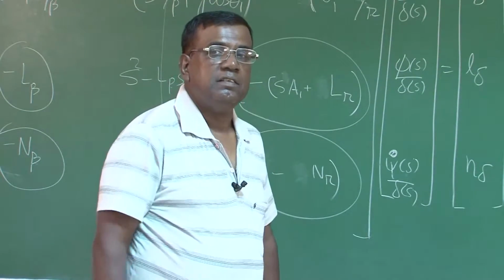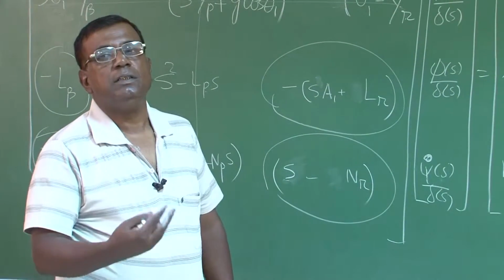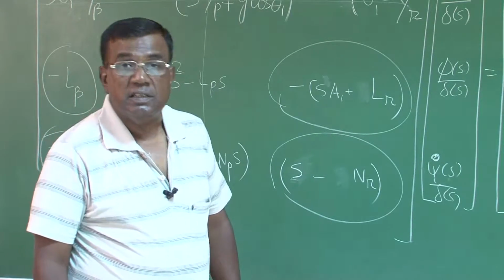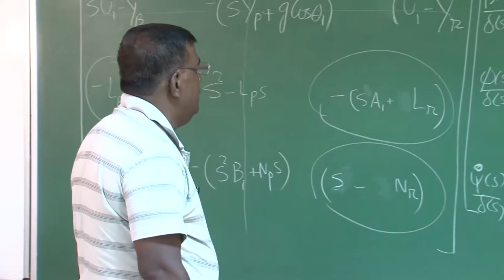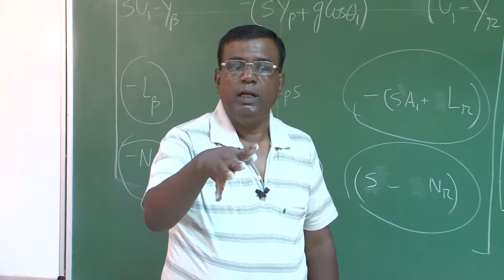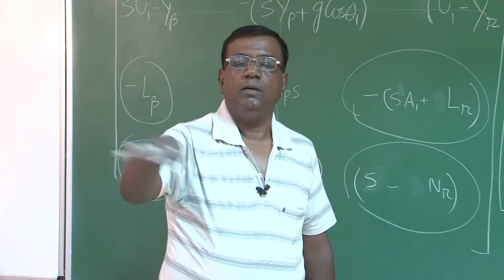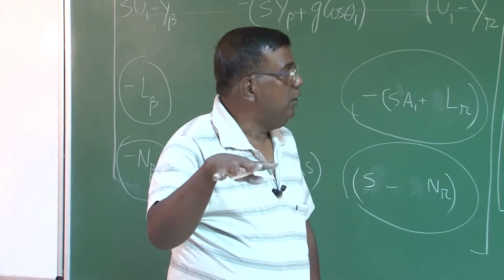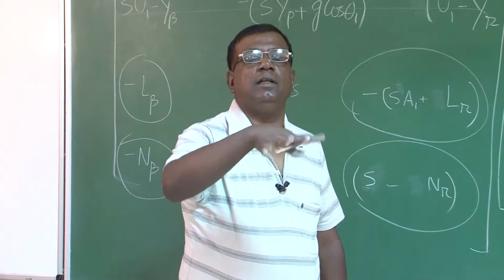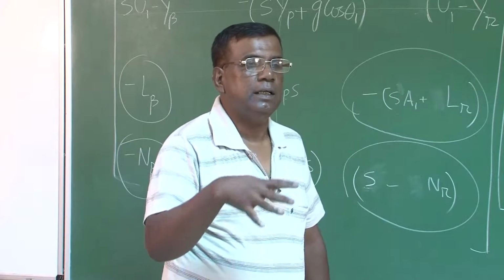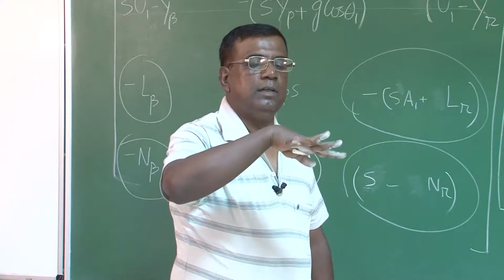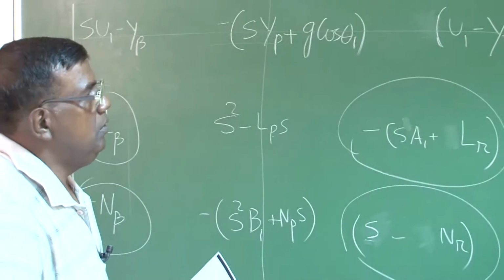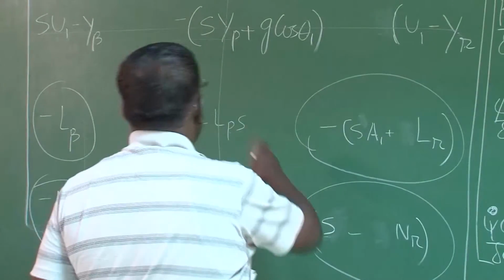That is, if I give a disturbance in the aileron, how is this aircraft going to respond to this rolling moment disturbance? The assumption is, if it is rolling like this, it is not affecting any motion in the y direction, no beta is introduced, and no psi dot is introduced, only phi, one dimensional. It is equivalent of thinking in a tunnel, you are given a roll disturbance and it is trying to build or decay, whatever it is. If you are doing only one dimensional roll mode approximation, then you are only keeping this.